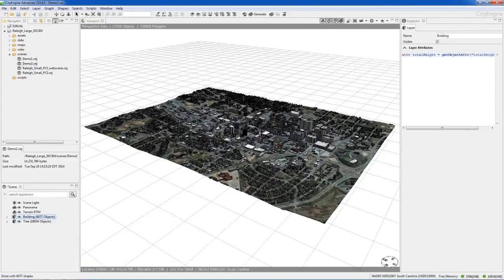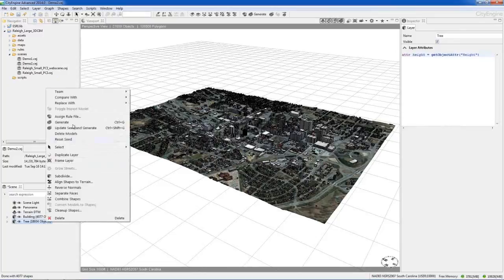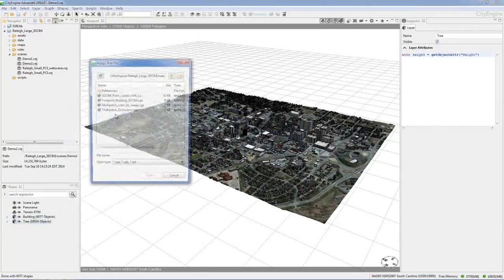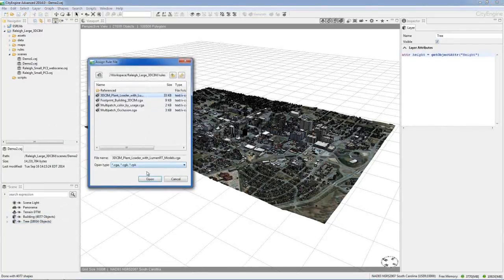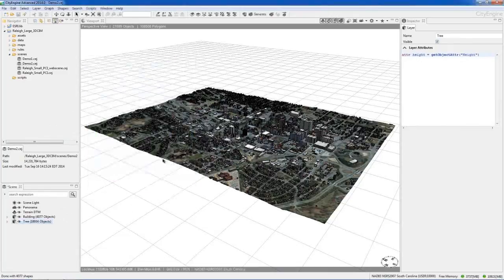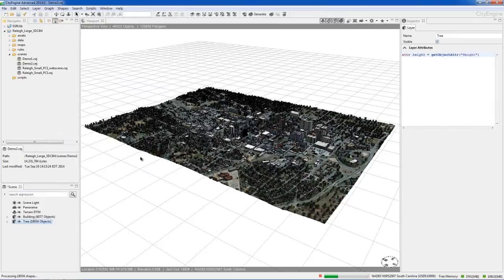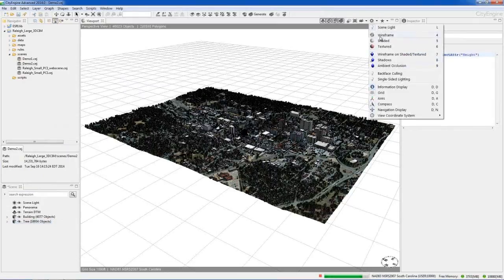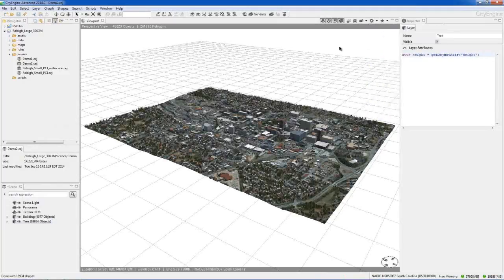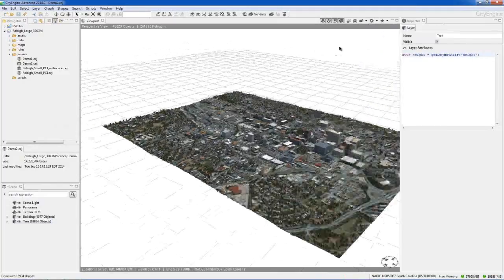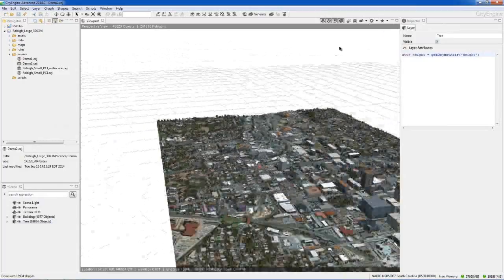And you see all the buildings just generated in 3D. Well, some other things that we can do is we can either extract tree points from LiDAR, you can use existing tree data, you can derive shapes where they need to exist out of your imagery with other processes, using different GIS processes, and you can scatter points across those shapes. And we can start to generate trees where they really are in the environment, or geotypically as to where they are, and derive the heights of this vegetation from these digital surface models from LiDAR, or that you can create with PCI's tools.